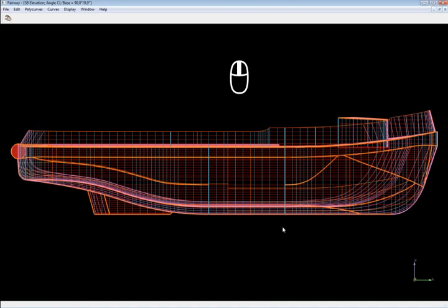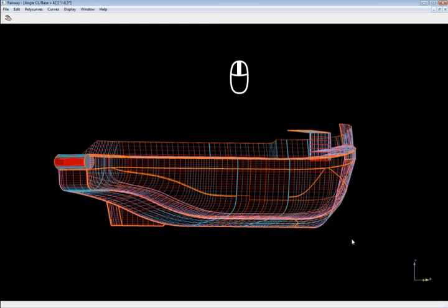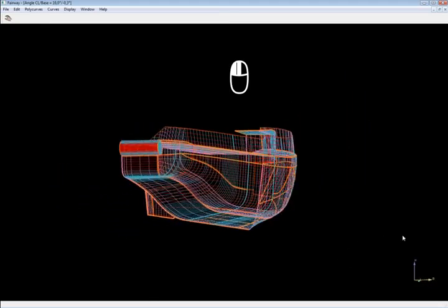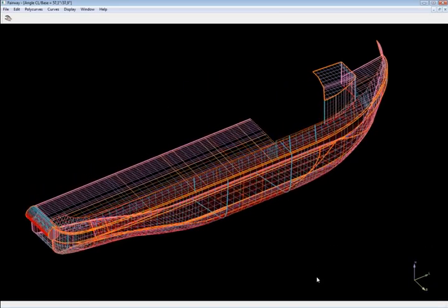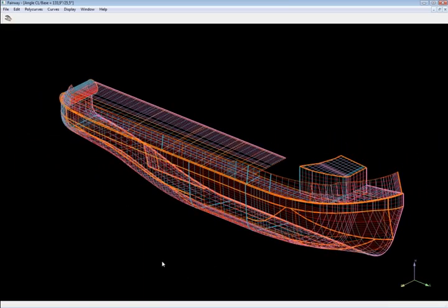Now on to rotation. Rotation happens by using the middle mouse button in combination with the shift key. For mouse-only control, just press and hold the middle mouse button and press the left mouse button in addition. The relation between mouse movements and rotation axis in Fairway is different from most other CAD packages, and we've got feedback that it's also more efficient.